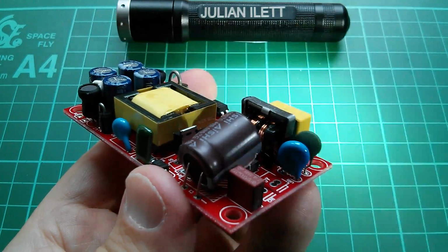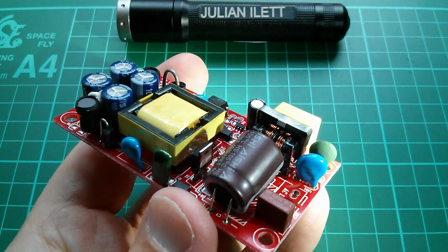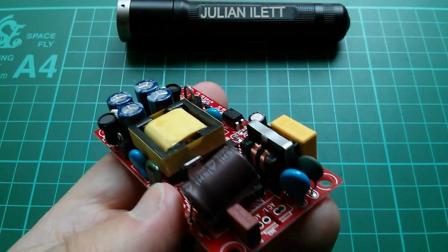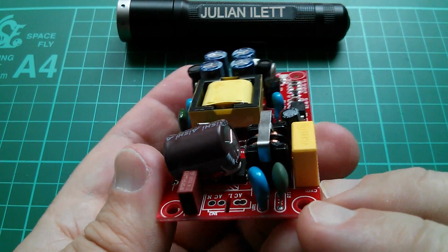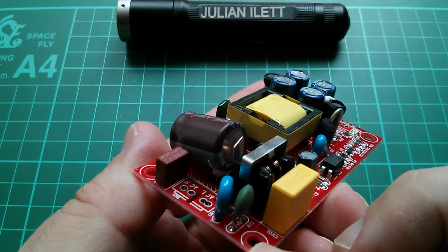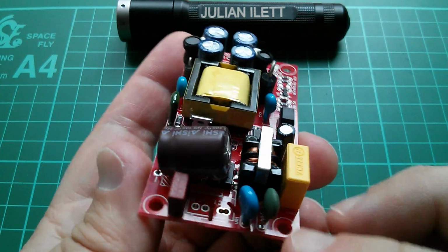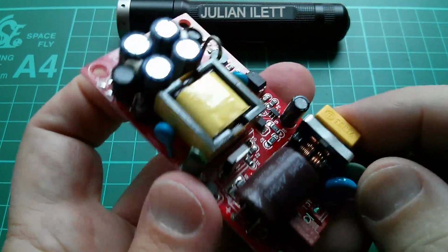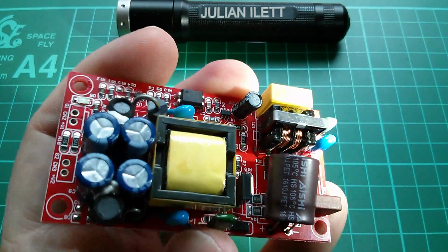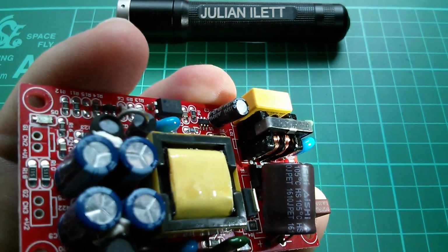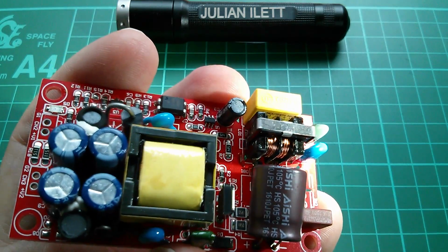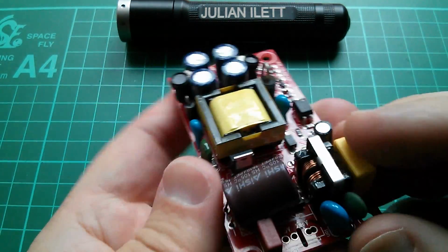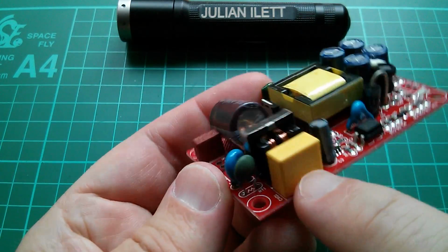It actually says VR1 on the board. Then behind that there's something that says NTC, so that'd be one of these negative temperature coefficient thermistors. So these presumably are both to deal with inrush current. That says RT1. So coming around from there we have an X class capacitor. I think down in there you can just about see it says X2. It's not very easy to see actually. So that's a class X capacitor. That'll be across the mains.